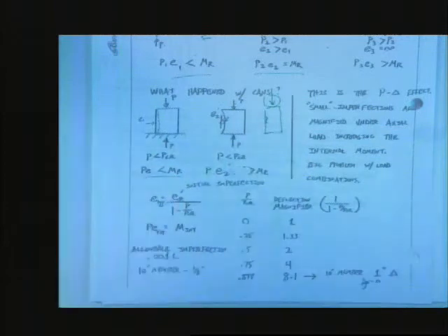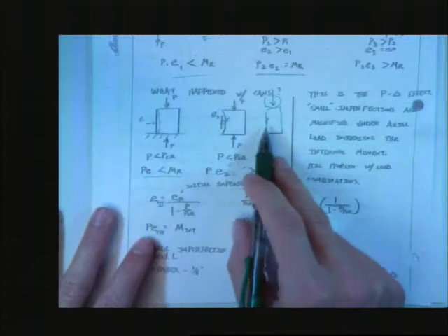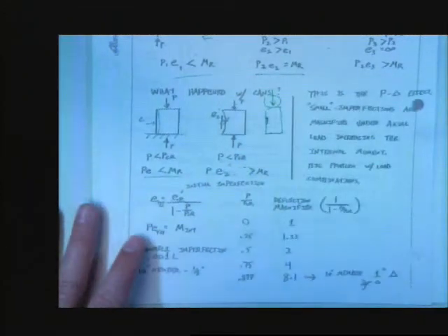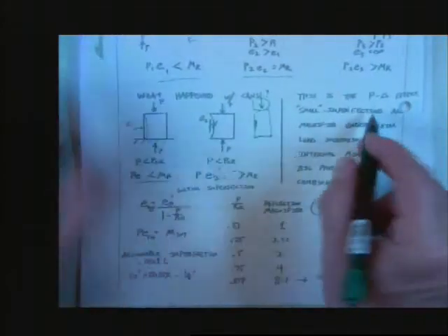Why? Because buckling depends on imperfections, stiffness, and geometry. Nothing to do with strength. You'd say, hey, this can wasn't any weaker. No, it wasn't. It just had an imperfection in it that was magnified. You with me? Awesome. This is something we call the P-delta effect.